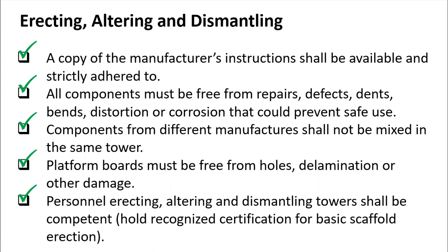Of course, you need to also provide competent supervision to check the progress of works and whether the work is being done correctly. If the person is competent to do the job, they can immediately recognize the unsafe practice, the unsafe parts of the scaffolding, or the unsafe condition of the area before they start, so they can make rectification before continuing.